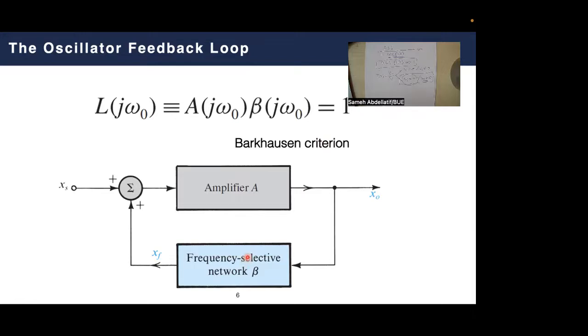because simply this is a frequency selective circuit. Please remember the last video related to resonance. Herein, you are not going to have this infinity transfer function everywhere in terms of frequency. No, it's only at a selected frequency that this condition occurs. So only for the selected frequency, an infinite transfer function will be generated, which is the concept of an oscillator. That's why we use the term L(jω0), to specify that this condition of L tending to 1 will occur only at a specific oscillating frequency ω0.